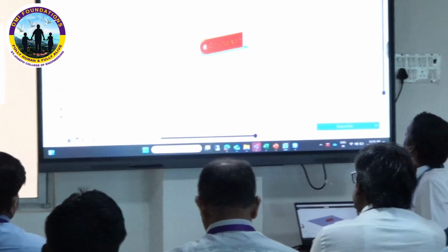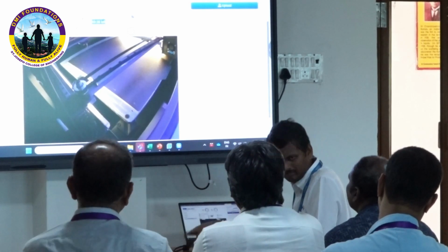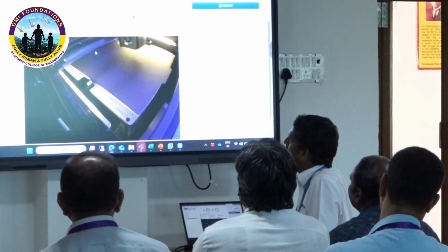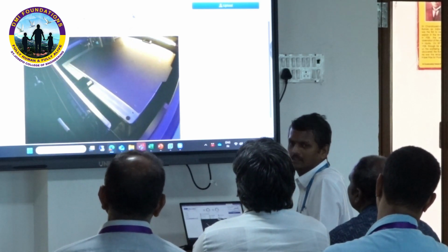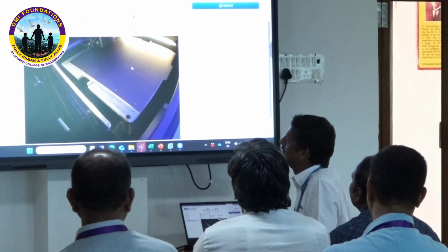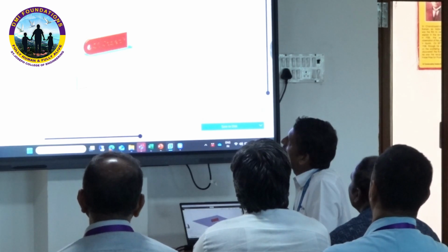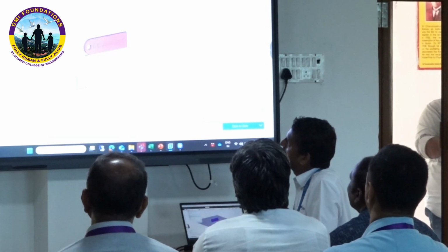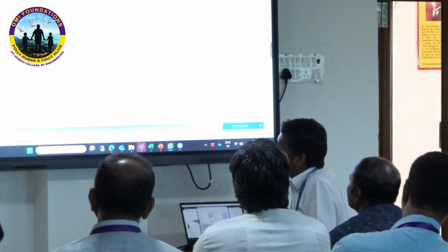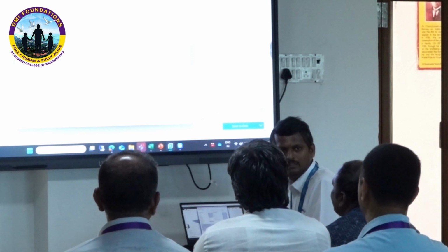Actually, we plan the slicing time plus the machine movement time. Everything is getting calculated. Now, 3-point bed leveling is happening. Every time it will do this, because here we have given it. Here in the printer machine settings, there is a start G code, right? Here you can see 3-point bed leveling. We have G34 here, which means it is going to do bed leveling.